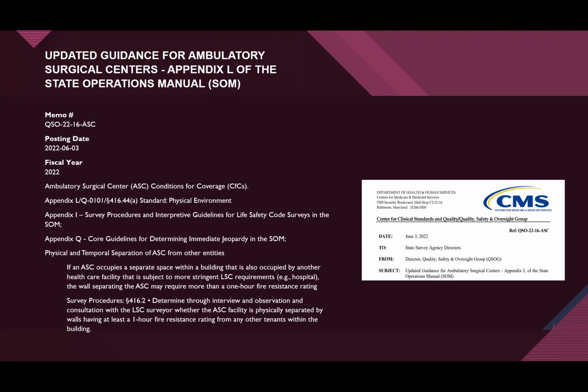And then the Q talks about immediate jeopardy, which is different from patient safety in that we are talking about building immediate jeopardy. And so physical and temporal separation is something I see that people have some confusion about. And so if you have an ambulatory surgery center, then only the ambulatory surgery center can be in the waiting room and can be in that space while the ambulatory surgery center is open. You cannot share corridors, supply rooms if they are within the 1 hour fire rated area of the ambulatory surgery center. And so the whole appendix L and Q and I are written with, this is the standard.